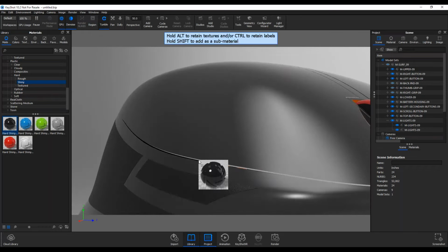Okay, yeah, so once you have this, you can also adjust your lighting. So if we go here, you can see that we have it on the basic setting, but we could go to product, which ups the quality level here. Same thing here with the interior mode, right? Let's go back to product, and that should be sufficient for this. And then there's also settings to adjust your environment.